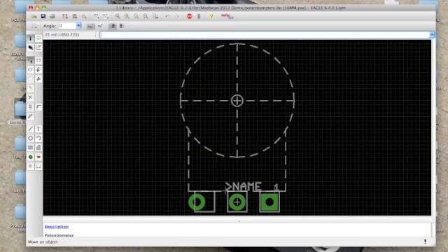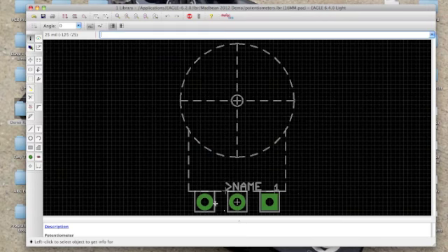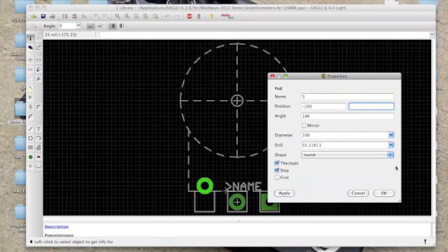Now, my graphics aren't correct anymore, so I can move these. Look at that. I just moved the whole pad over. I'm going to undo all that because we know that it's actually supposed to be 0.2 inches. But you see here, just by selecting the info tool on the pad itself, we get a bunch of different control. We can move this up 100, apply it, see that? Now it's moved around. I'm going to undo that. Oh, 0, apply. Okay.